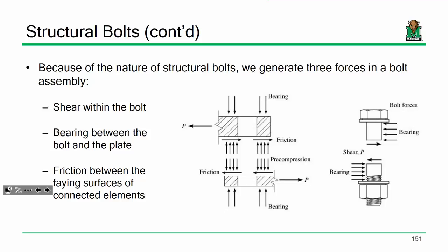You've got steel connected with steel. There's a coefficient of static friction. You can get some frictional force developed between those two plates. You can actually rely on that for design purposes, which we do in cases like bridges or cases like earthquakes.